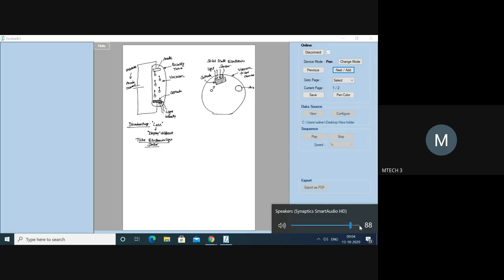The thing now is, please understand, the electrons generated here do not have enough energy to give you a sufficient amount of anode current. So what we'll do now is we will have some device which I will call a dynode. I am going to call this dynode 1. Dynodes are called photo multipliers.